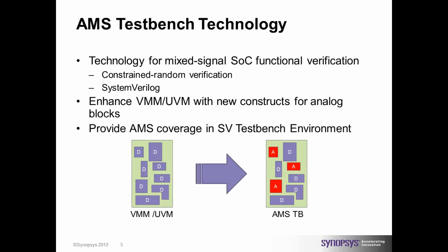Okay, that brings us to what we mean by AMS Testbench Technology. Having a test bench for AMS components: if you look at the diagram below, on the left hand side is the test bench which has completely digital components in it, and we have very set and defined methodologies and language constructs to be able to do verification.